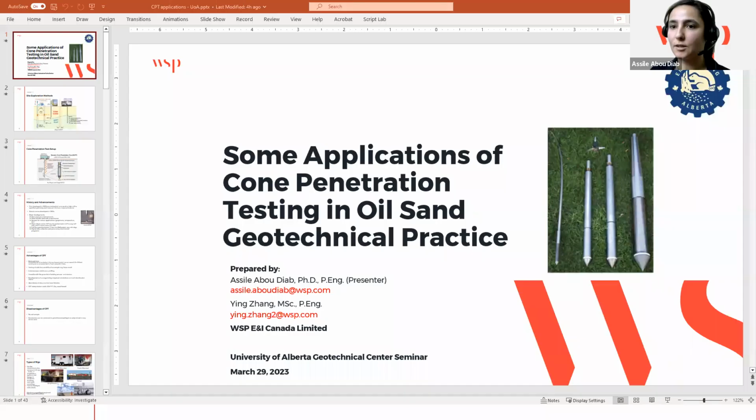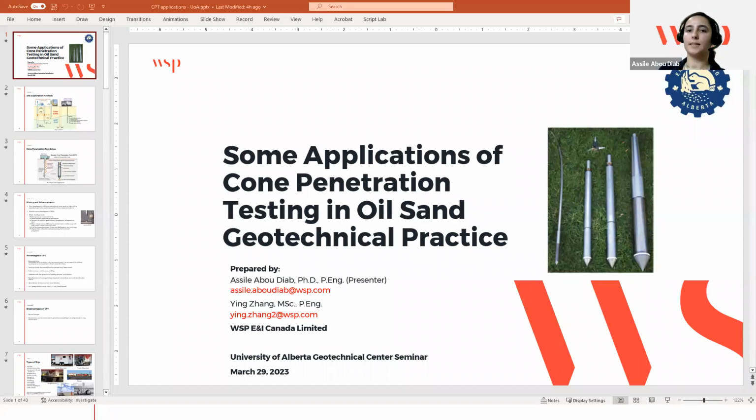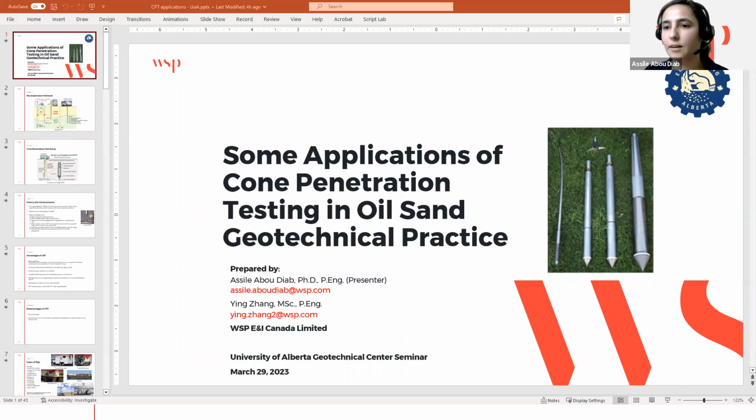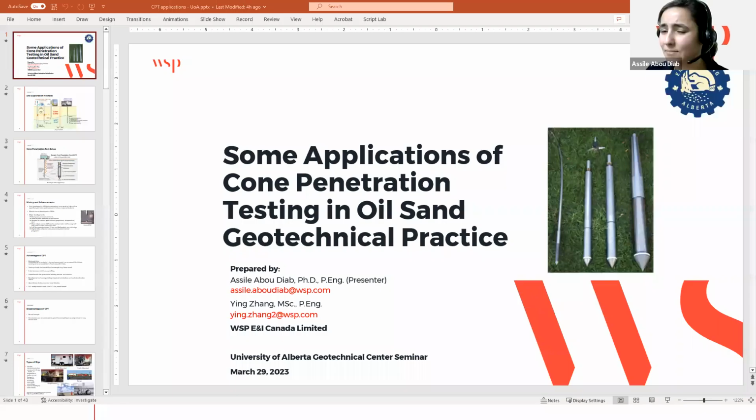Yeah, so actually we have a yearly performance investigation going every year. So we have an extensive program of CPT, vane shear, and other in-situ tests, and we keep monitoring the tailings to check how their strengths and characteristics are evolving with time. Okay, great, thanks. So if it's an annual program, I'm assuming then the rate of consolidation after those wick drains have been installed, you kind of have an idea on how that's also accelerated.